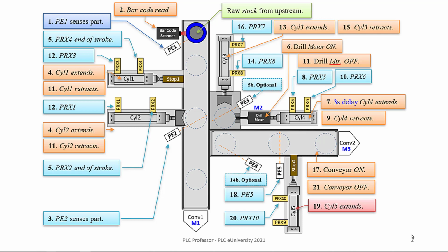Once it's all the way into the part and through to the center area or the depth for the hole, it stops for a moment, pauses while it augers out the debris from the hole, and then cylinder 4 retracts the drill motor with bit back out. It may or may not continue spinning to make it cool off faster. It just depends upon your production rate. Then once all the cylinders are clear, you have to retract cylinder 2.